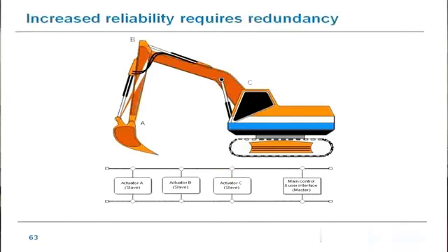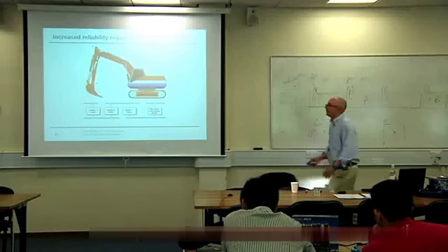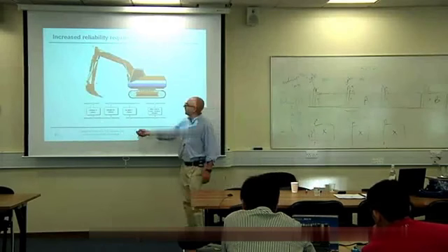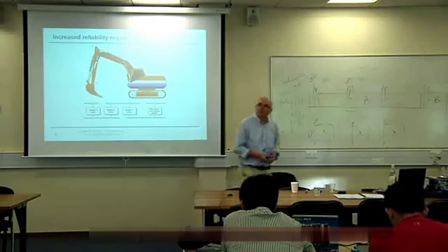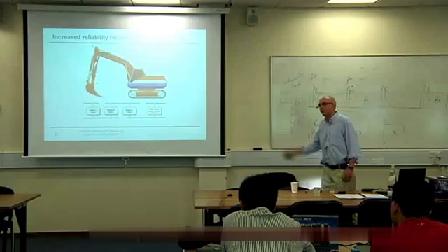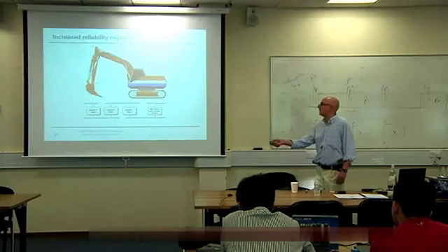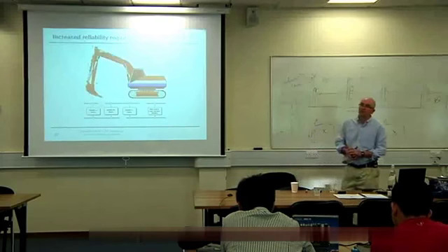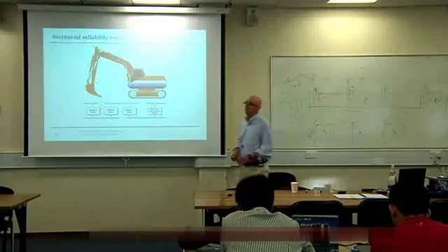We can duplicate the CAN bus. This is particularly common as well. Run a separate CAN bus down each side of the vehicle, whatever it is. This is great fun. Possibilities of breaks in the bus at different points, in which case these individual nodes end up having to route messages in order to keep the system operating. That's a nightmare in software to implement, particularly if you're trying to do so while ensuring you've got precise timing behavior. It's challenging to get that to work.